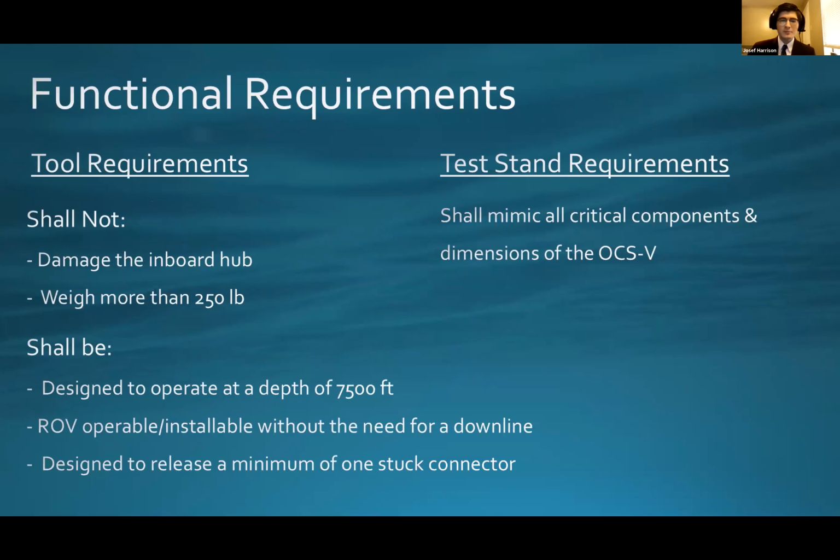Now, there are 3 primary areas of challenge in this project. The first is the material of the lead screw we need to cut. It's made of Nickel 718, or Inconel. Inconel is considered one of the most difficult materials to machine due to becoming both stronger and harder as it's worked. On top of that, this cut must be completed in under 2 hours as per the constraints given to us by OneSubsea.